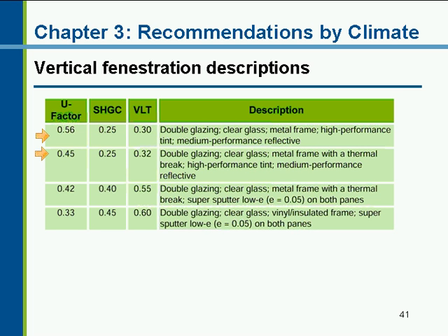Nowadays, people are starting to use some thermally improved frames where they're actually trying to bury a lot of the frame, the metal, inside the building, and then have the glass on the outside of that, and then there's just a thin little cap that is screwed through and attached to the frame. This way, the thermal bridging gets reduced significantly because it's primarily the screws that are going through from inside to outside, and you don't have thick pieces of metal going all the way through.